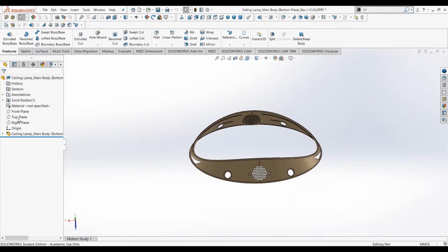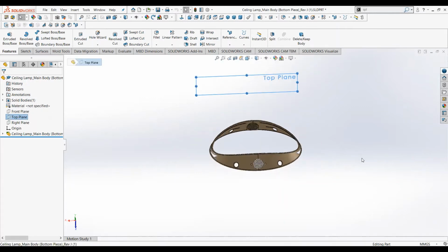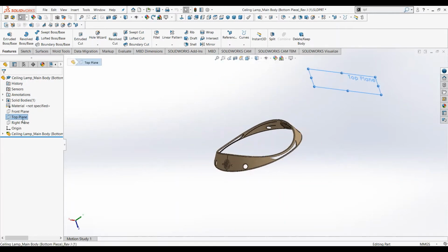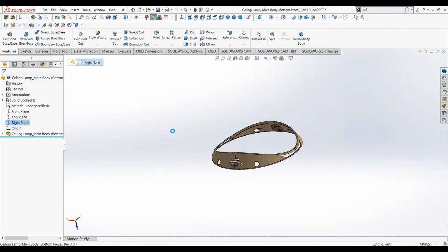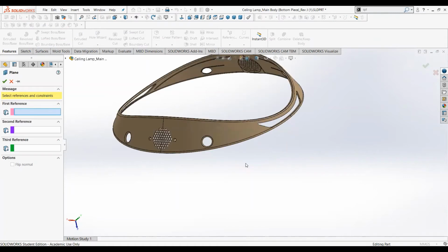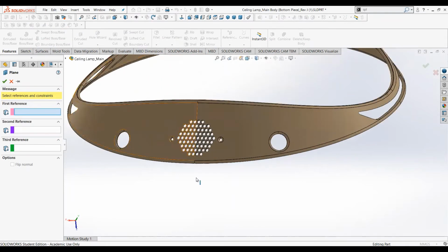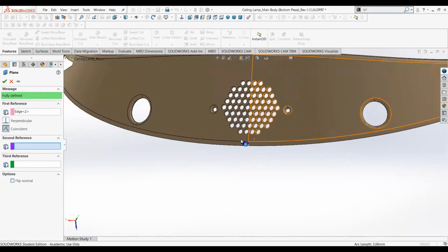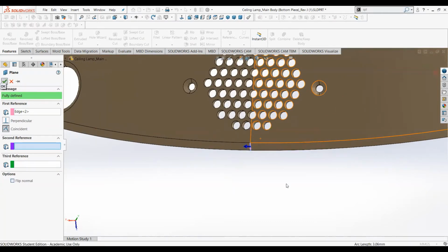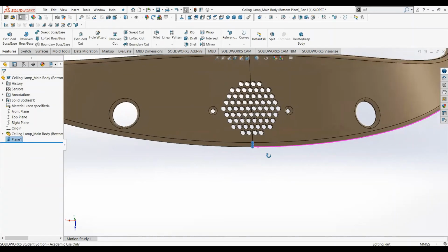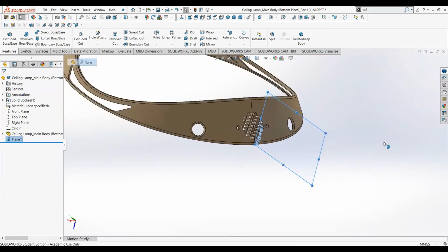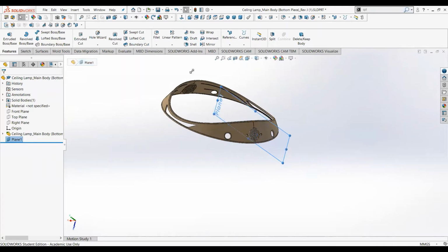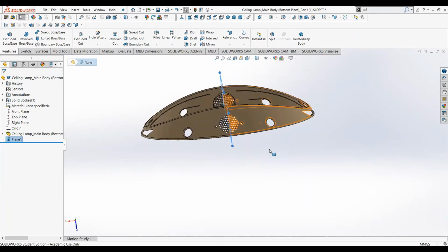But yeah, first we need to create a reference plane. So go reference plane, and I want to split it along this seam first. Okay, so this will be a fully defined plane right there. And for clarity, we can expand this. So now you know what the plane looks like, splitting the whole product in half.